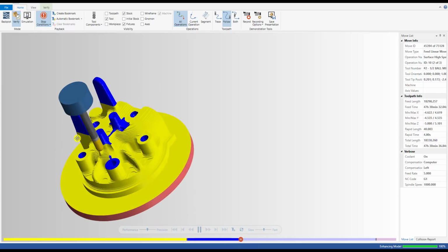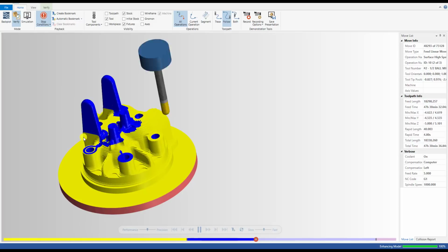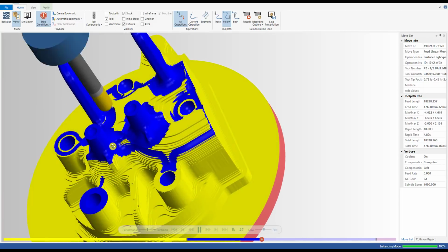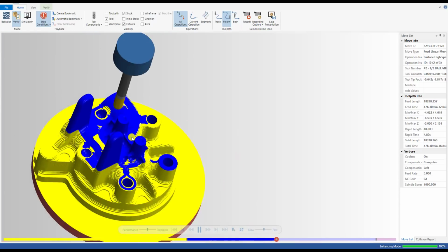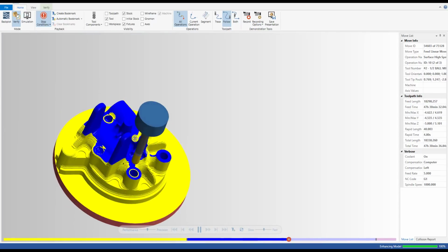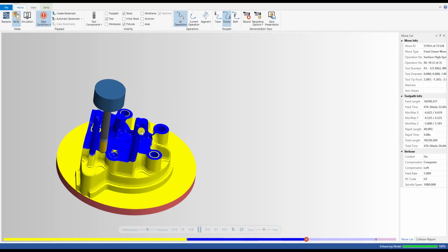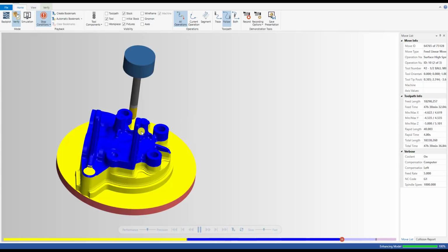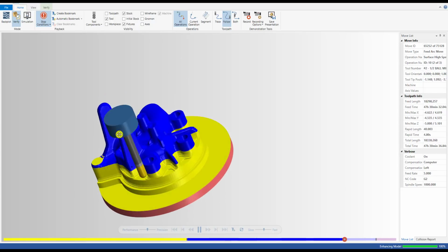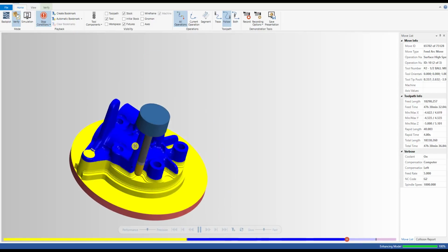Ooh, I forgot to patch the hole, so the tool goes into all of the holes. That's crazy. But look at the fillet. You can see now there's no longer any mark of the roughing tool. All marks have been cleaned. This is a good sign. You can see we don't have to create the fillet manually. We just modify the Toolpath and everything becomes much better. Okay,